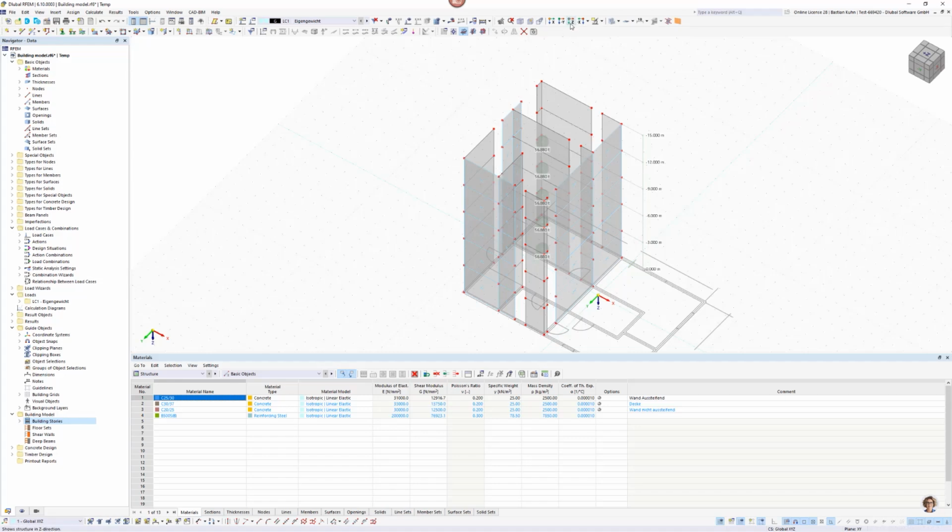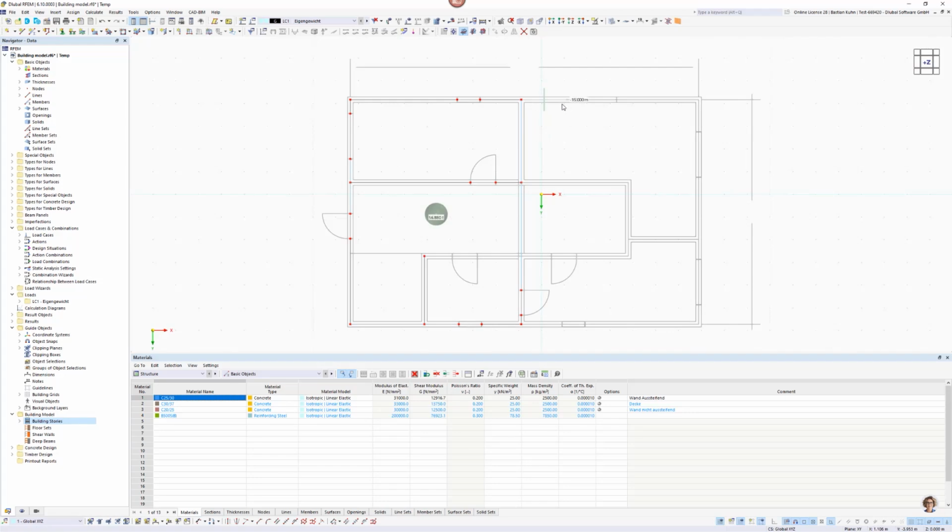So, and of course, I said in this case we will need a few more posts and maybe we will put some kind of drywall or a masonry wall or something like this on this part in order to reduce the free span, because if I do not activate these walls in here, I will probably get problems with the deflection and the vibration of my structure. So I will proceed with the columns.